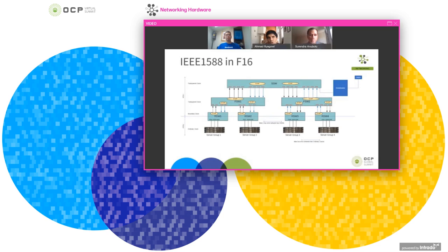The correction that the servo puts in is with respect to the hop, so in the case of the servers, it's with respect to the boundary clock. You look at the previous data and you see there is a correction, let's say within 100 nanoseconds, while the boundary clock itself is within, let's say, 500 nanoseconds from the grandmaster.